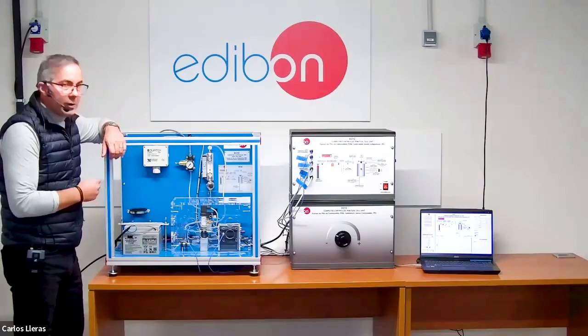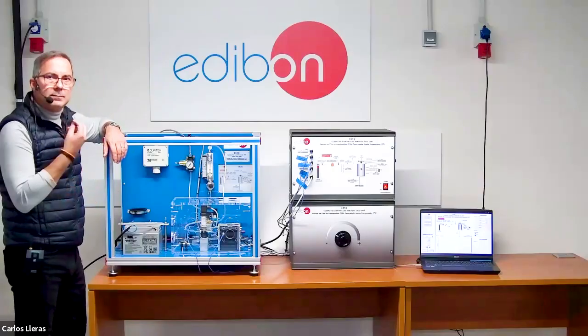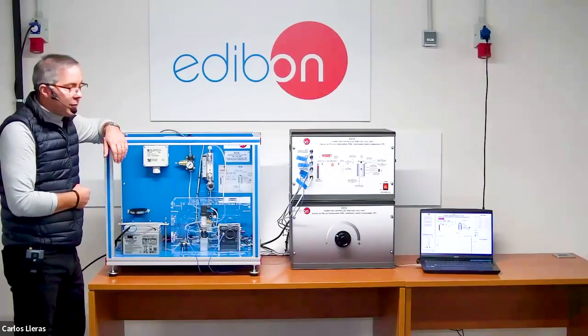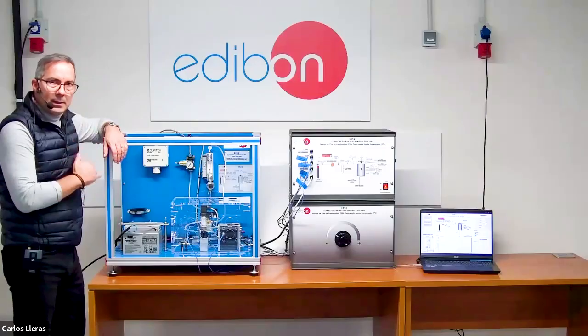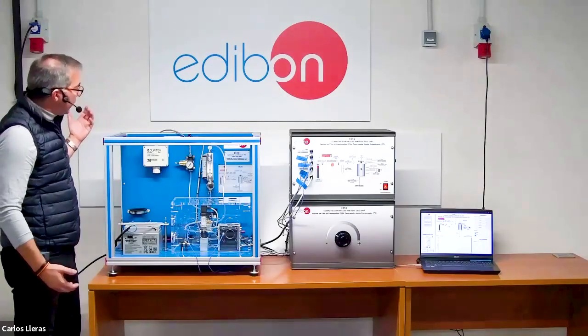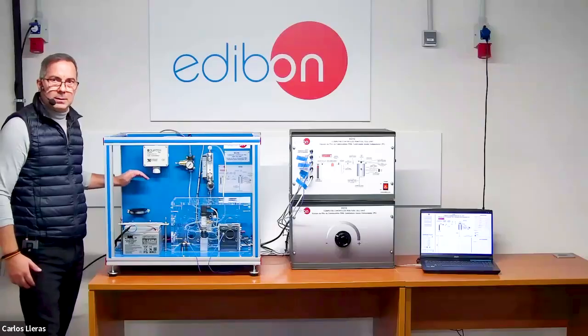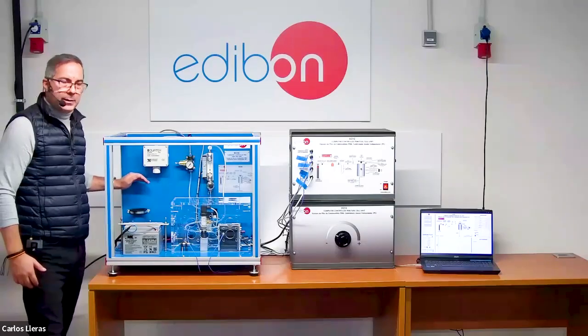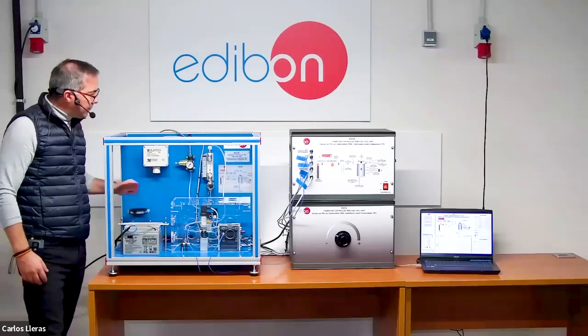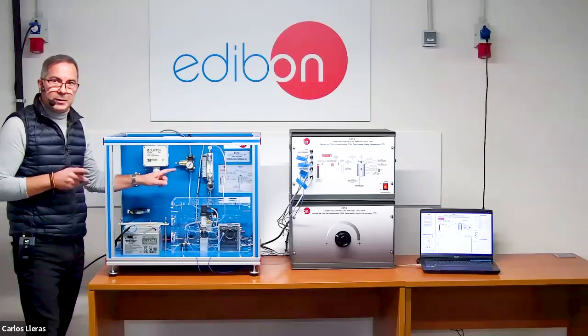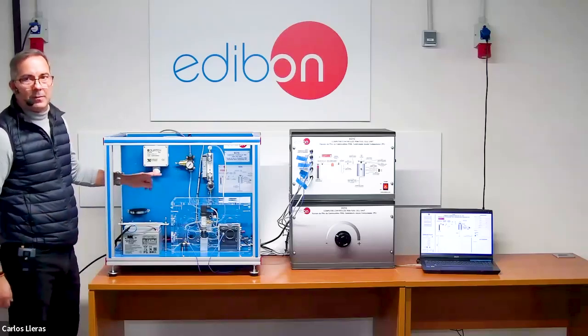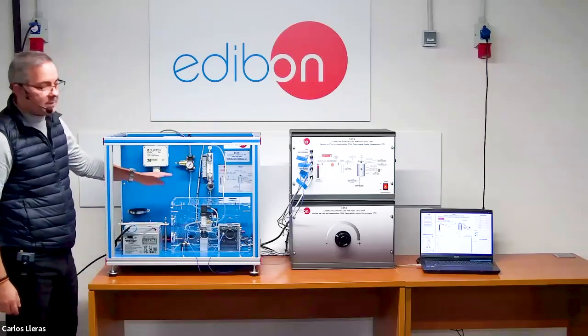So this unit will obviously require a hydrogen gas inlet. There are two ways. In this case, you could either place a hydrogen bottle right here, through a regulator that can be connected directly to the unit to provide the proper amount of H2, which is hydrogen.